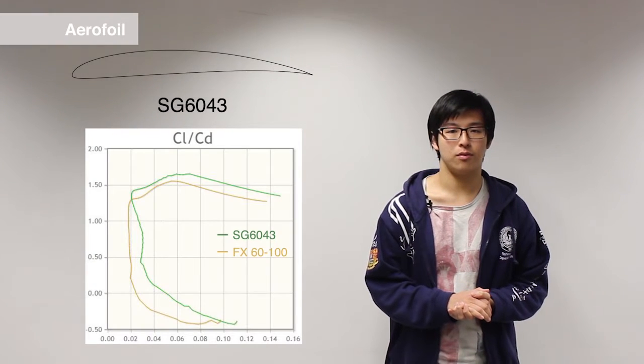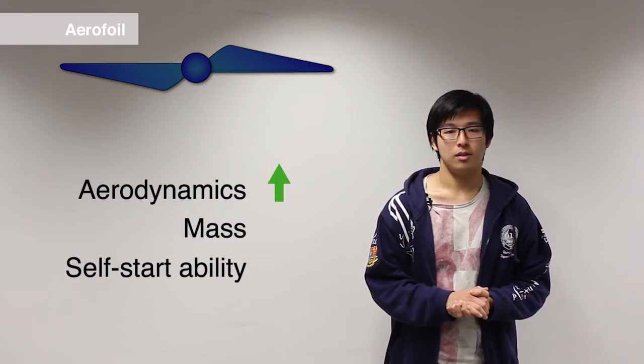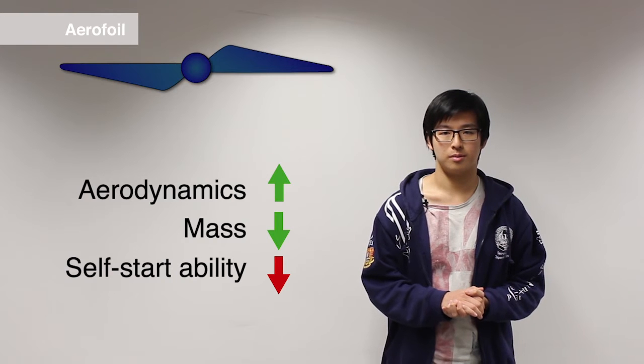We finally chose the SG6043 airfoil for its high optimum lift coefficient, at which lift-to-drag ratio is maximized. This allowed a narrower blade profile for a two-bladed design according to Schmitz's distribution. It resulted in the blades being more aerodynamically efficient and having a lower mass. However, it also reduced the blade's capability to self-start.